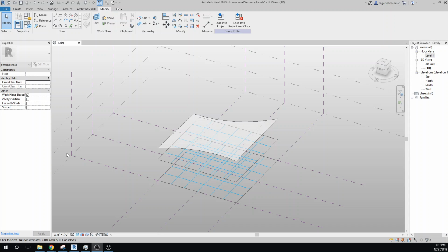Okay, we're going to start our space truss with a work in the conceptual mass that will allow us to create our roof form that we're going to apply our truss to. We're also going to create two additional layers so that we can apply structural columns that we're going to make, some custom tree-shaped columns. And we need to delineate the spaces with some kind of reference grids. And this is all happening inside of the conceptual mass.